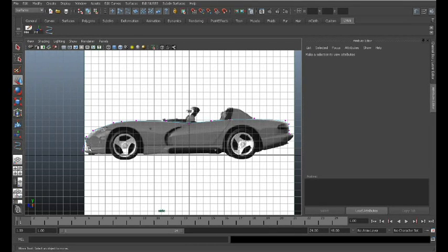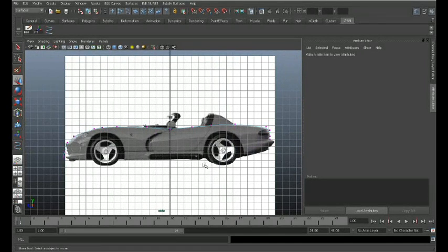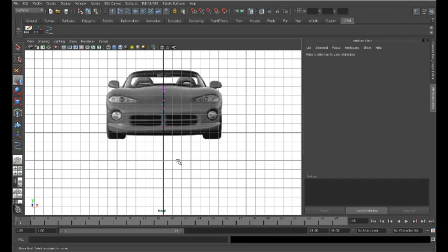Okay, we don't want a lot of curves and we don't want a lot of points. We just want to keep the resolution as low as possible. So when I go in here and try to find those areas to define, I'll want to hit the high points or the low points in those particular areas that will help me define this shape. So once I have the side view, I'm going to go ahead and check it in the front view.